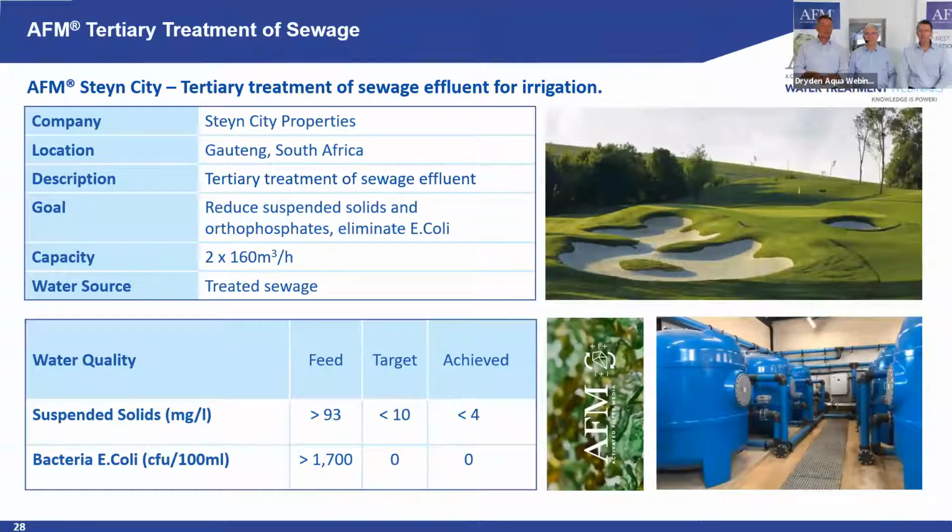You see here what they achieved. It's a tertiary treatment of sewage effluent. They use it for irrigation. Suspended solids in the feed water 93, and after filtration below 4, and E. coli 1,700 down to 0. So very well done.